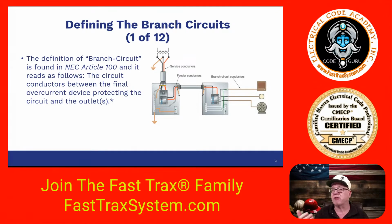You're going to see references to outlets like lighting outlets, which is basically the box that a luminaire would mount onto, okay? A receptacle outlet. It's a box where the power of the branch circuit is coming to, and you're actually connecting it to a device that you put in the box so that we can plug in attachment plugs to other types of appliances or utilization equipment. So it's so important to understand the different definitions, and I encourage everybody to take the time to really look at definitions in Article 100 and really get to understand them.